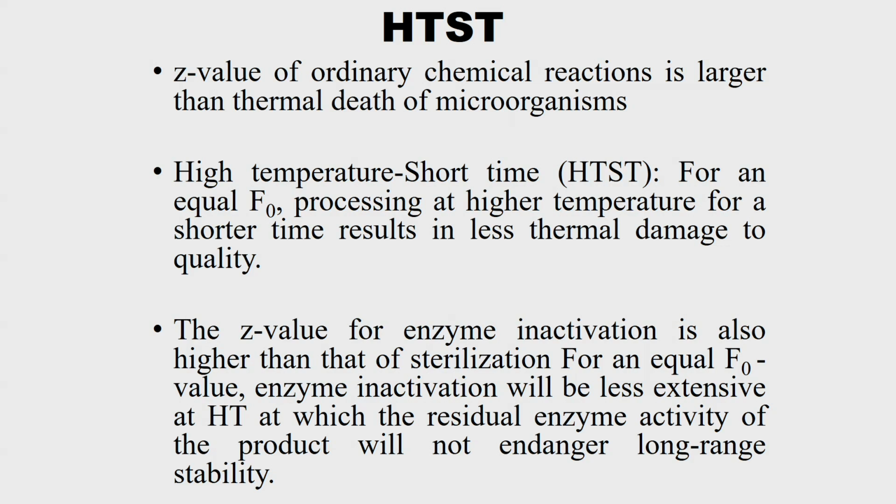We have already seen some examples, and we discussed a lot about the Z value. If you remember the kinetic expression classes, we also compared two cases, the vitamin destruction as well as the microorganism inactivation. In that, if you remember, the Z value for any ordinary chemical reaction is normally larger than that of the thermal death of the microorganisms, right. For that case the concept of high temperature short time is introduced, right. For an equal F naught also, we have already discussed in the class, the processing at high temperature for a short time, right.